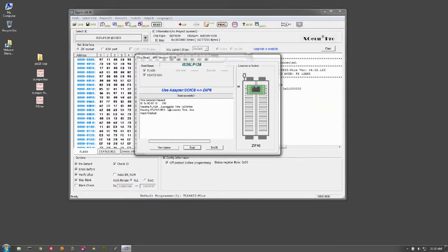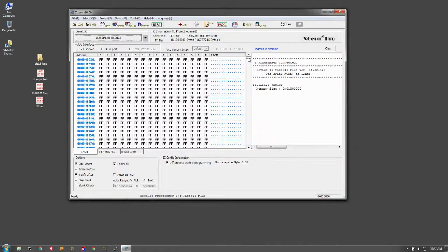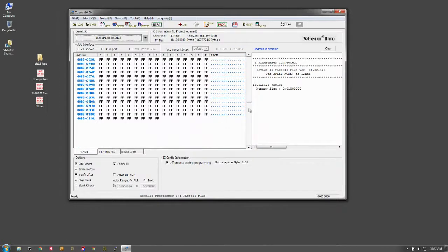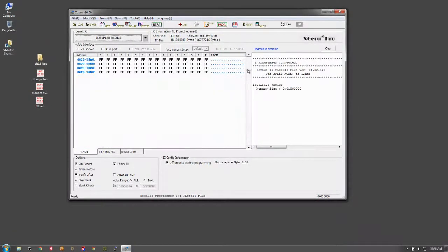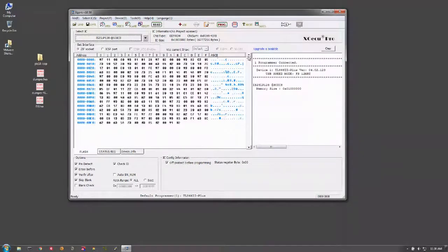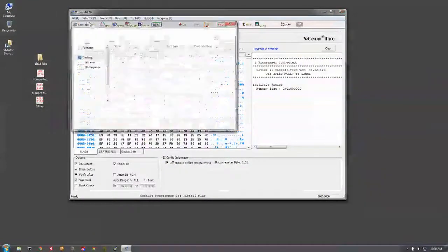Okay, so reading the flash, read finished. We can close this, and now we can see here a little hex editor view. It turns out there's the bootloader in the first section of memory, and then way down below, there's the user code. But because this is 16 megabytes and the code is very small, it's mostly Fs, but then there's some data. So let's save this and see if we can view it in a different way, just to give us an idea about what's actually there.